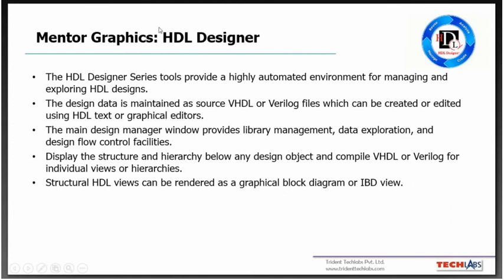So HDL Designer is one of the beautiful packages in Mentor Graphics. It is a very good software for learning, and especially if we are new to coding, we can develop our own state machines and we can automatically generate VHDL or Verilog code. And the advantage of HDL Designer is it can integrate with other simulation as well as synthesis software. So we need not worry about launching the software separately. We can directly launch from the HDL Designer interface as well. So today I will be linking my Questa Sim with HDL Designer software for simulation purpose.